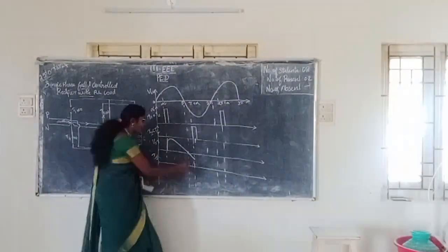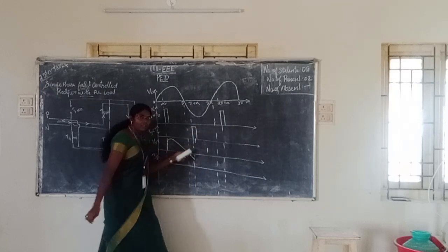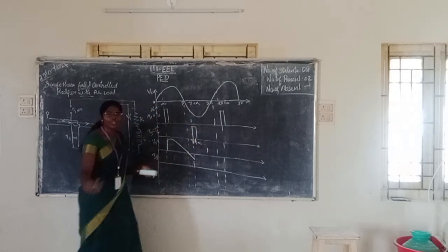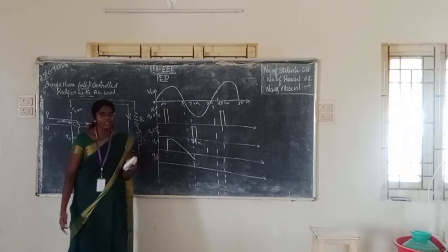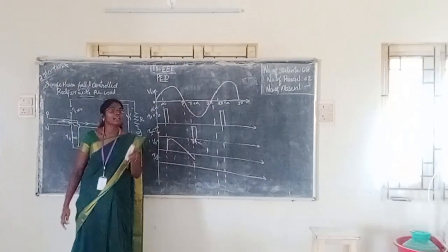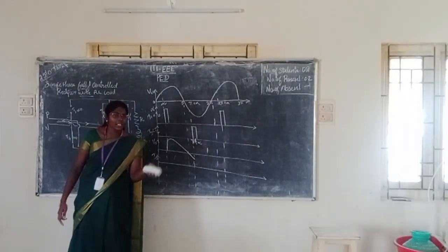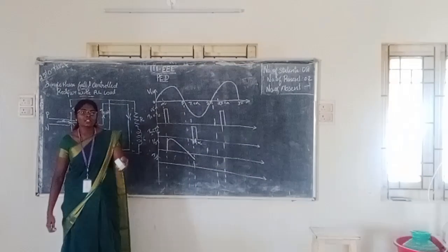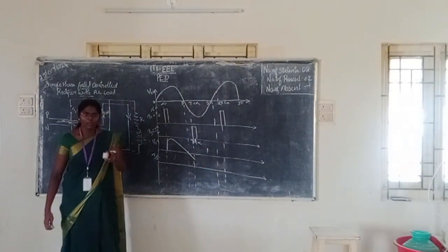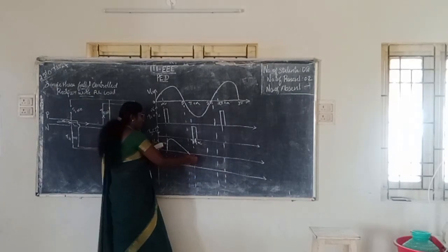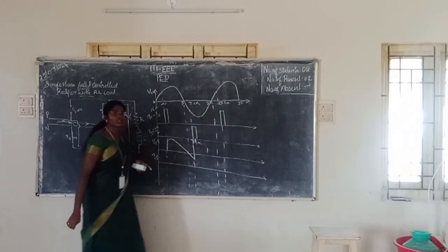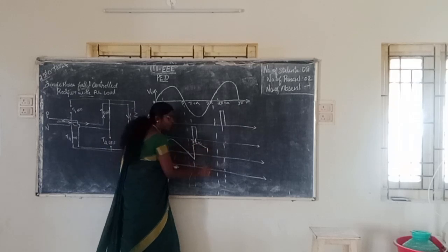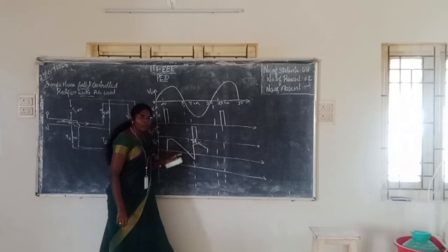After that, next, at pi plus alpha again, there is a continuous conduction mode. Continuously the conduction is starting by the triggering of the switches. T3 and T4 are in the on state. Again the voltage will start to rise. Can you follow me? So again the voltage will start to rise like this, it will reach the same level, and this process will be repeated.